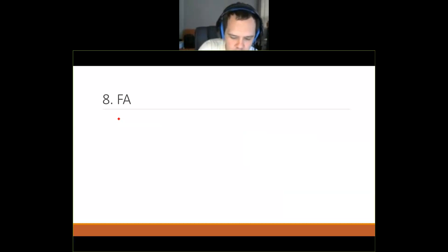My unit volume in this case is going to be 1 cubic foot. Now, what I'm going to do is start subtracting out each of the known quantities, and basically any volume that's left over is going to be my fine aggregate. So first off, I'm going to go to my air. That's the easy one.